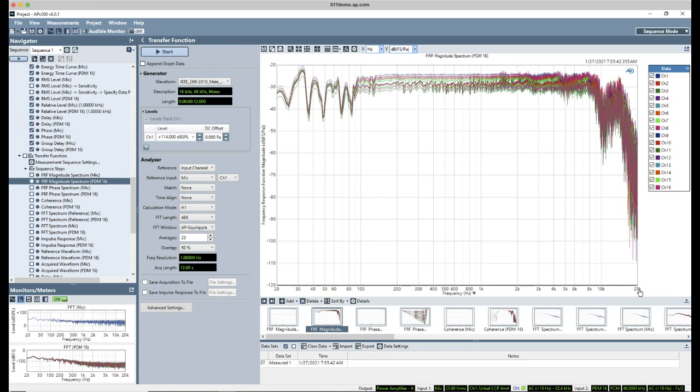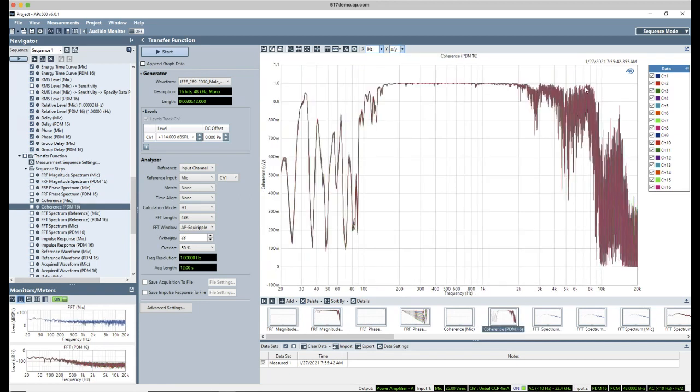And what I have going on in my transfer function is a couple issues. First of all, in the sweep, I'm starting up here. But the second thing is, going back to my coherence result, my test signal, the actual speech I'm playing back to calculate the transfer function, doesn't have significant energy above 10 kilohertz. So that's getting reflected in the results. My results with this particular test stimulus are not valid above 10 kilohertz because I don't have energy above 10 kilohertz, or in fact, very much energy below 100 hertz.